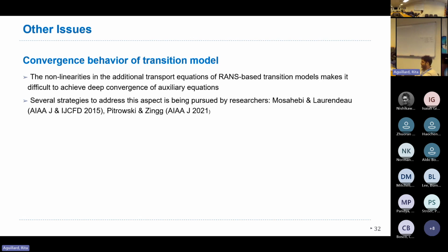And you're finding those two independently? Yeah. Interesting. Adding the prismatic layer for the initial part and having different resolutions near the wall changes the profile for stability. Because I think we saw this with the metric-based adaptation as well. Like when Nate was doing it, it was adding a lot of grid in that region, but it didn't help us in terms of stability. So there is some sweet spot where, of course, it's maybe not as important near the wall.